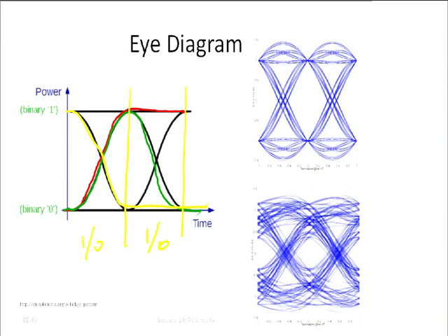And so in order to quickly evaluate whether a cable, for example, can go at whatever speed it is, 10 gigabits or whatnot, communication circuit designers make this plot here. This is called the eye diagram, and then they look at this eye, and they look at how much white area there is. If this area completely closes, you have absolutely no way anymore to determine whether you had a 1 or a 0. Here the eye is still a little bit open.